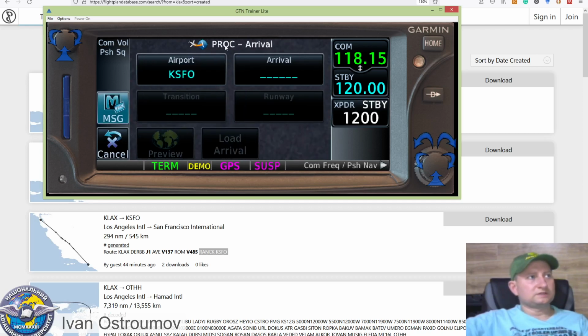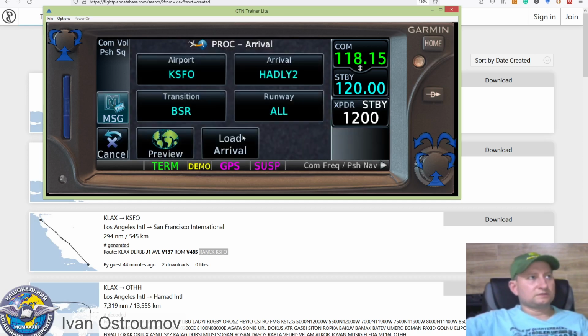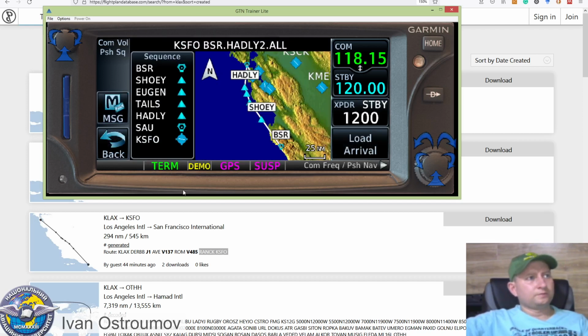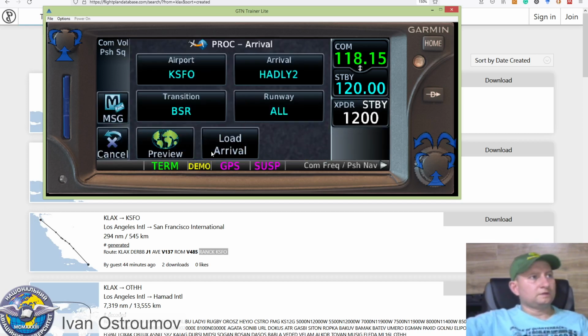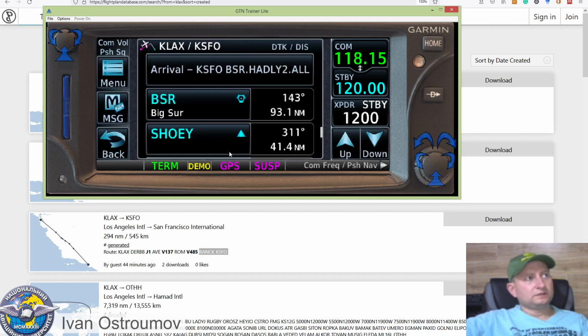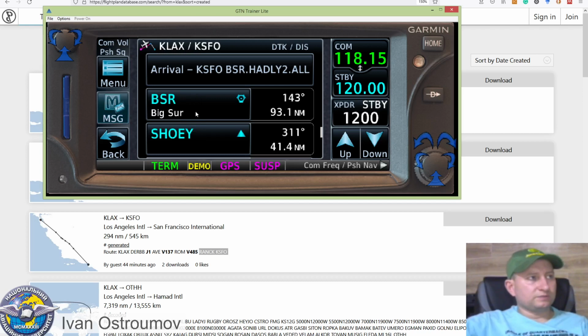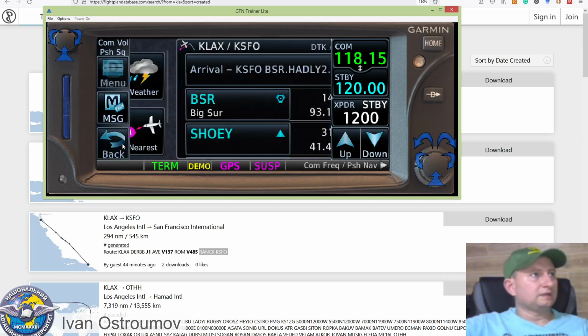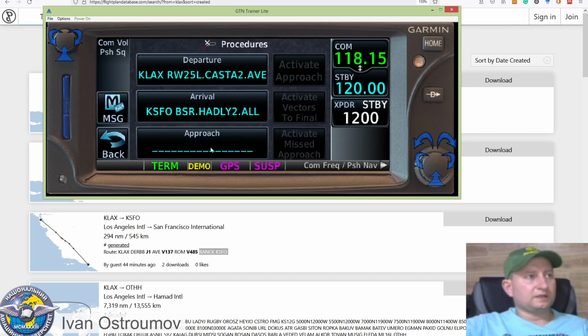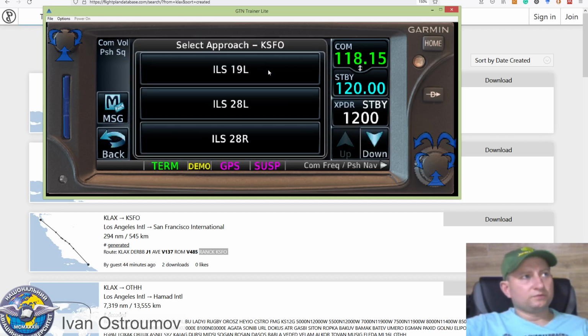We need to set up arrival for San Francisco airport. Let's choose one of them. Then click preview. Yep, why not? Yes, I agree. And just click on load arrival, and we will see arrival at San Francisco airport with the following sequence. That's why specific waypoints have been added to our flight plan. And if we click back and go to procedure again, we can set up approach scheme for KSFO.